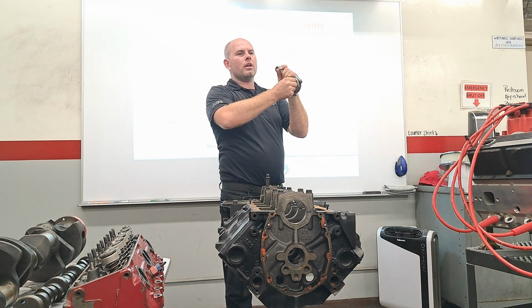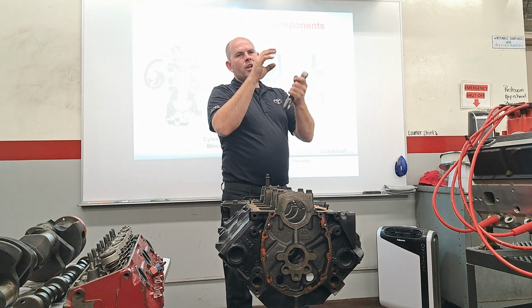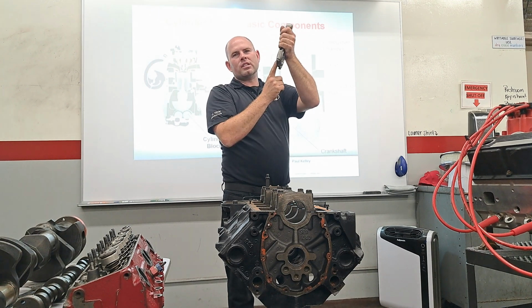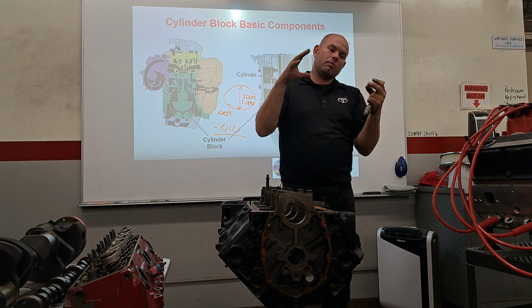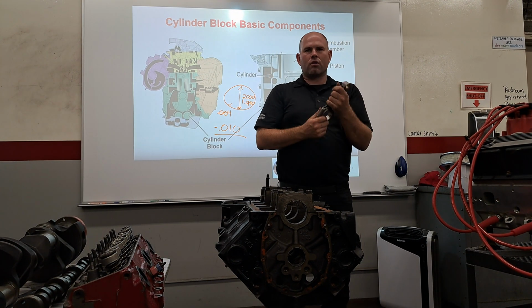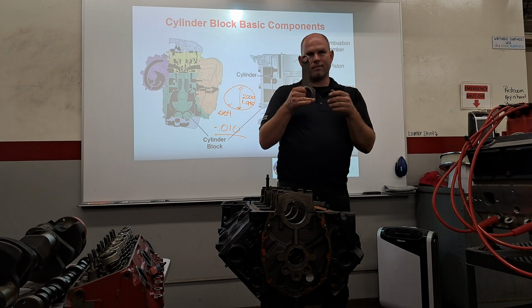So if we were to resize this 10 thousandths, you could get a 10 thousandths oversized bearing, while also potentially having it be undersized if you cut the crank too. See how that's kind of crazy? And then here on the top we have a piston pin.